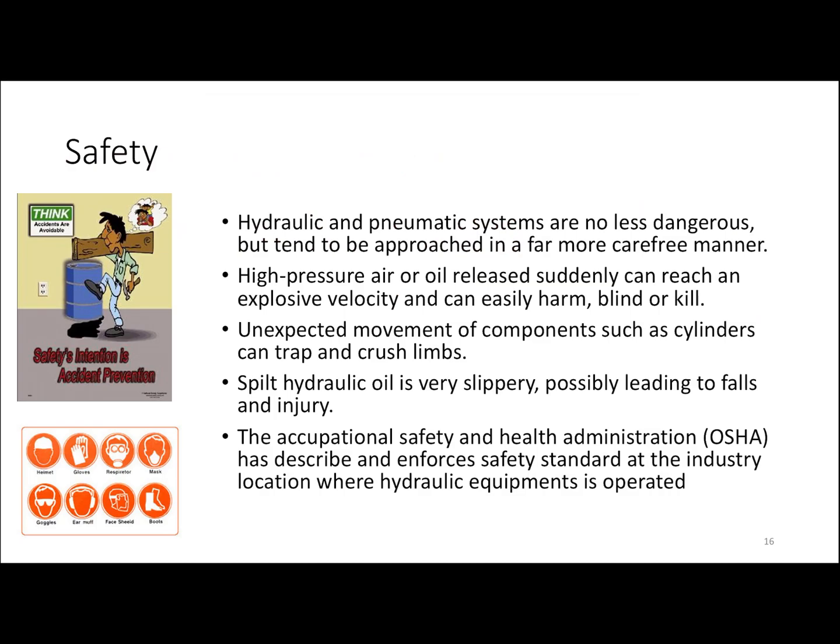Also, unexpected movement of components such as cylinders can trap or crush the limbs of the operator. That's why in hydraulic and pneumatic systems we must ensure to install protective equipment, by designing the circuit properly, right? And in terms of safety, spilled hydraulic oil can be very slippery, which, if you're not careful and cannot see it, can make operators or someone around the hydraulic system fall,